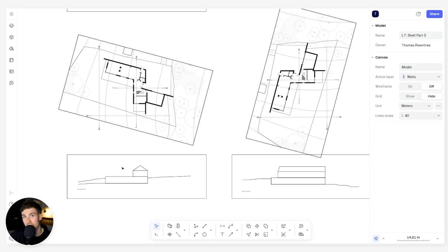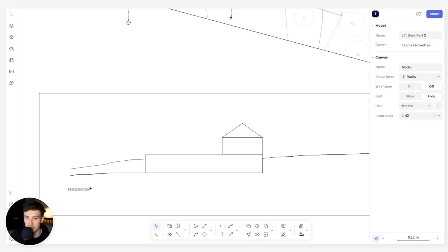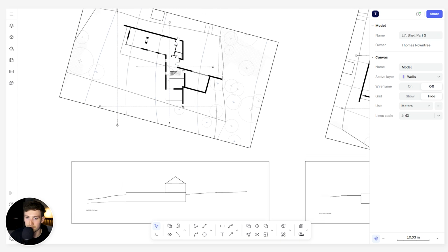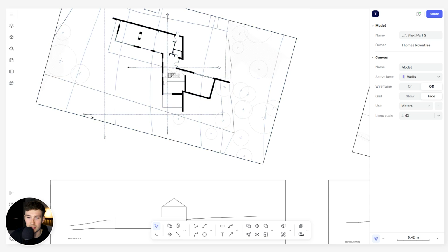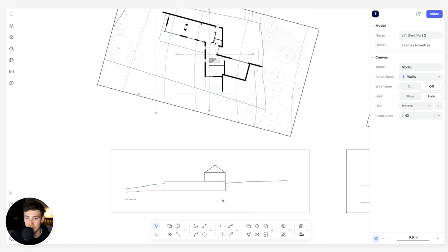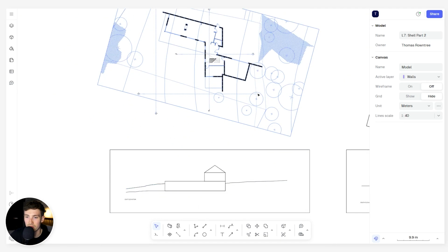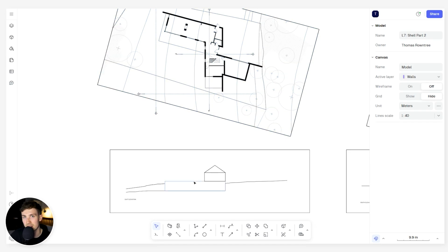And this will be a process of going back and forth between the floor plans and elevations, as I've discussed. So what I've done here is I've set up the two elevations, the east elevation and the south elevation. You're probably wondering why I've rotated the plans in this way, and it's simply because I have aligned the elevations parallel with the elevation line, so we can begin to essentially project the floor plan onto this massing and begin to define where these windows are being placed in elevation, where these voids, where these walls are being placed.